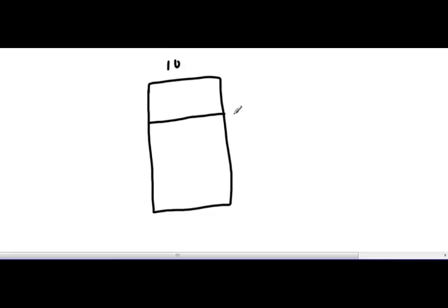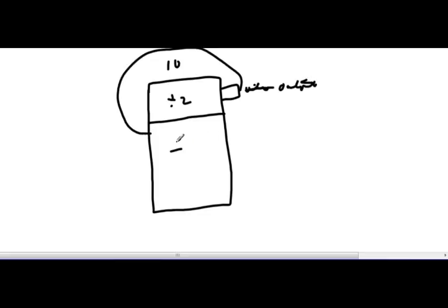So what's going to happen is that we're going to have one side, which is a divide by 2. And if we take the output of that divide by 2, and we send it into the bottom half, we get a divide by 5 out of him, and then the most significant bit coming out of the bottom, so that'd be Q0, 1, 2, 3, Q3. That would give me a divide by 10 of whatever signal I was sending in. So I got some input.